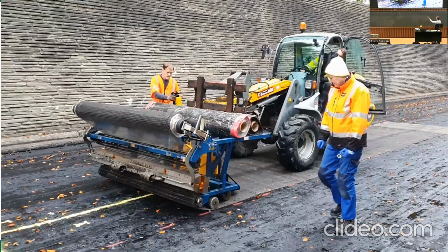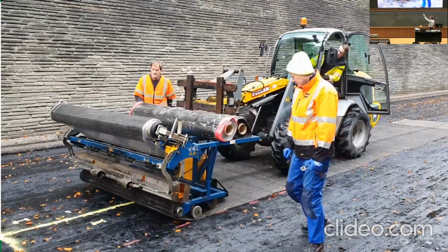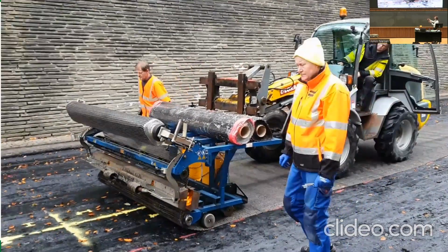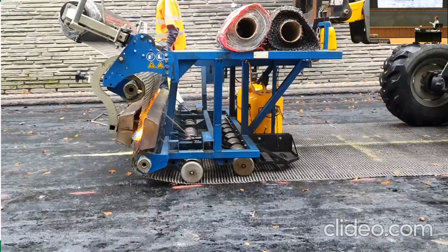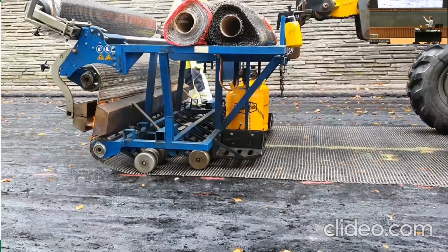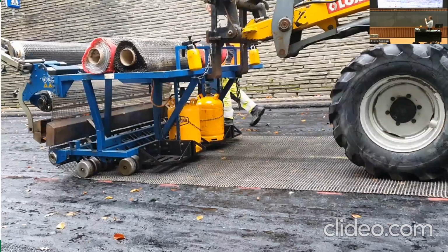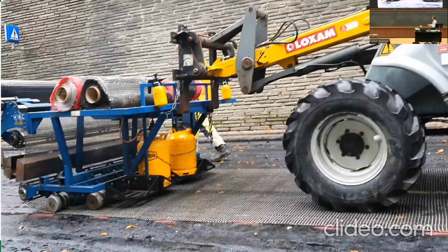As you can see, the grid comes in these rolls and is dragged through a heating area where the grid is heated up. The bitumen changes its property and becomes softer. When it's pressed to the ground, it sticks because it has been heated up. This is super important for later installation: we need good adhesion between the grid and the surface it's applied on, because when the asphalt paver comes, you don't want the whole thing to be dragged up by the wheels.